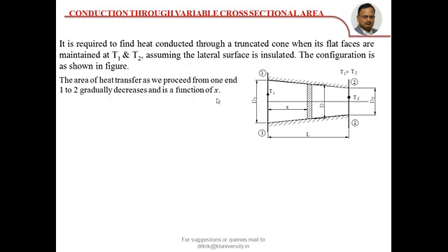So now heat transfer through the entire cone from bottom face to top face is say Q. The heat transfer passing through this elemental strip is also equal to Q. So we will write the expression for this elemental strip, and then we integrate it over the entire length 0 to L. So for this purpose of getting a relationship of how the area is varying as a function of x, we will now consider this entire cone.